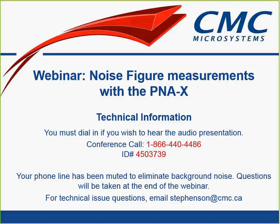Today's webinar is a one-hour presentation by Maury of Keysight Technologies on noise figure measurements. Noise figure is a critical figure of merit when designing components found in modern communication systems. You'll start with explaining the noise figure fundamentals and describe the common noise figure measurement techniques used, and continue by introducing the cold source technique implemented in the PNA-X system. We will then describe the vector and scalar noise figure measurement techniques used to measure amplifiers and receivers.